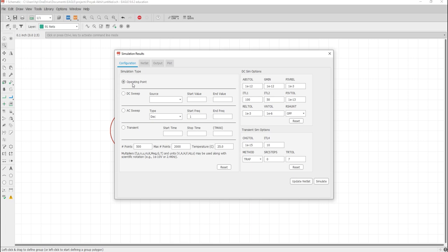There are currently 4 supported types of SPICE simulation: the AC, DC, transient, and operating point. If you choose an operating point type simulation, you need not change anything else, and you can just click the simulation button. An operating point analysis is useful when you want to view information such as voltages or current levels at startup.